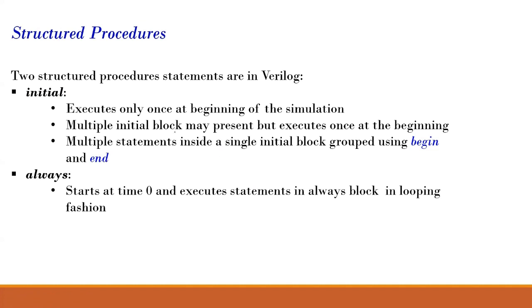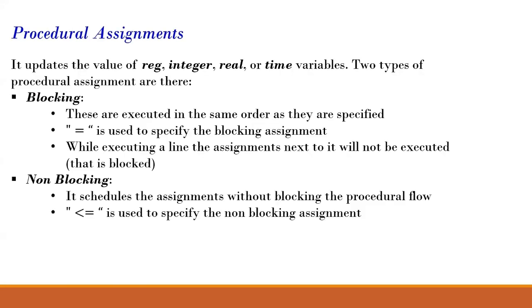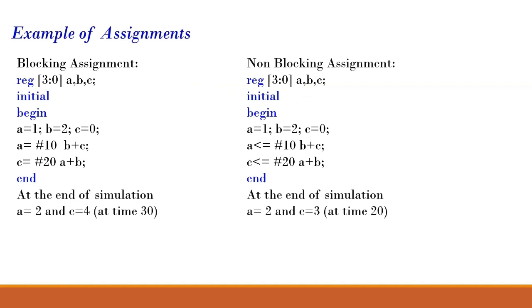So now there's an initial block. It is like initializing certain variables. We are initializing them with values for the initial thing. And then always blocks are implemented in a loop, like a while loop. If you have used a microcontroller, we have something known as a while loop. In a similar way, the always block is in a looping fashion. These blocking and non-blocking assignments we had seen.